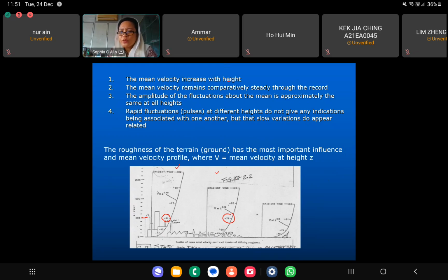And then the third wind profile is the more extreme one, in which you are in the open area or facing the seaside. There is no obstacle for your structure when it comes to wind, and the wind profile is more pronounced. You can see here, it is even bigger like this, and for the same height, now you have 91 mean velocity of your wind.